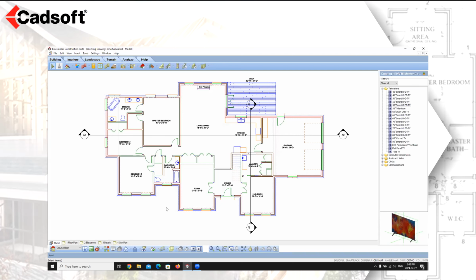In the document that I'm going to be sending you, there are a list of different scales for different types of drawings that you could be creating. As an example, when you are inserting elevations, elevations can be set to 1/8 of an inch scale or a 1/4 inch equals a foot scale.